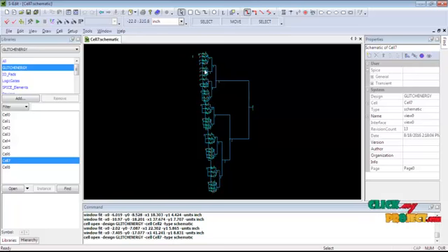After that, the D flip-flop output is fed into the BWCS, that means the binary weighted current switches current steering digital to analog converter block. The BWCS DAC converts digital to analog. After that, the analog signal is compensated using dynamic compensation. After that, the output will be displayed in this specific window. Then simulate the corresponding window and the output will be displayed.